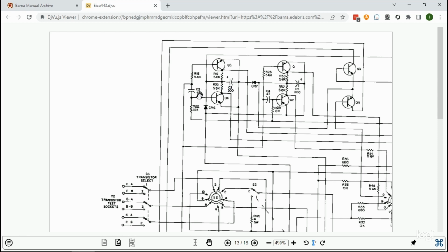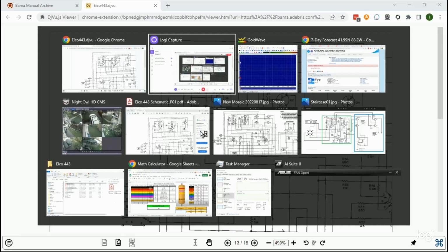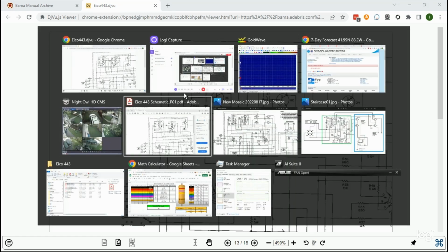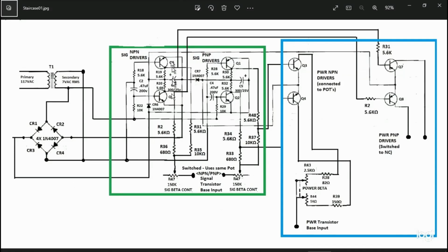This is a 0.47 orange drop capacitor, and you're missing your decimal point. A lot of stuff like that happened on this scan. I was just going to look over here. Q5, Q6, Q1, and Q2 are our staircase generator transistors for the signal level. So Q5, Q6, Q1, and Q2 are paired, and in the schematic that I made, that's what I have.